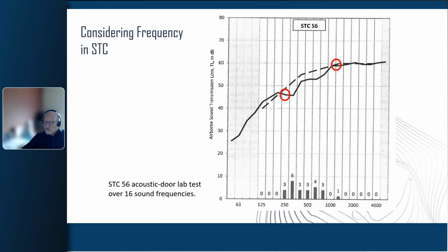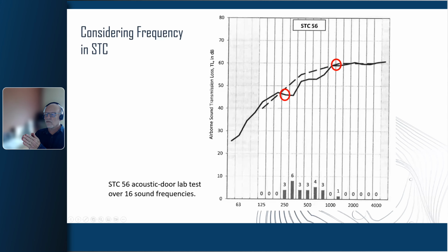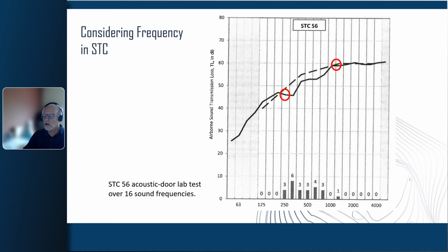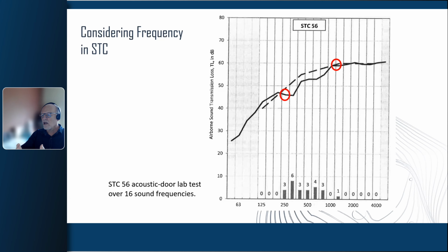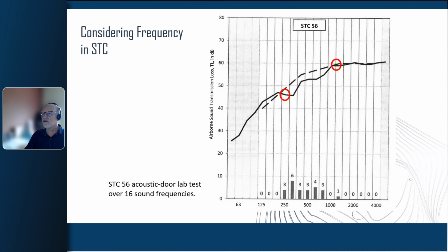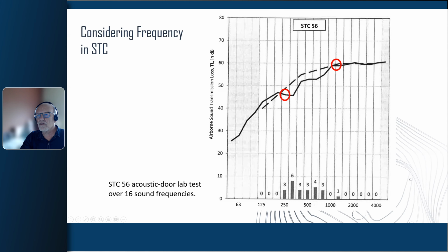This reference to hertz is the amount of times, it's spelled like the car company, Hertz, and the reference is the amount of times that a sound wave goes past a certain physical point. So again, going back to the door frame assembly, the door is open. That point is the door threshold, the frame around the opening. Low frequency noise, the double bass, goes through that opening at 250 times per second. But high frequency noise goes through that opening at 4,000 times per second.